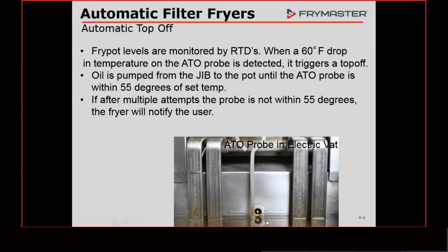If after that minute it still doesn't reach that probe, it's going to shut off again, regroup, and then it's going to come on and run. It used to be, on a split pot, 4 minutes. On a full pot, it was 6 minutes. That may have changed. We had a lot of software changes over time. That seems like an awful long time to have that thing run. It may have dropped. Subtle changes like that, they don't necessarily tell anybody, because you're not going to notice it.